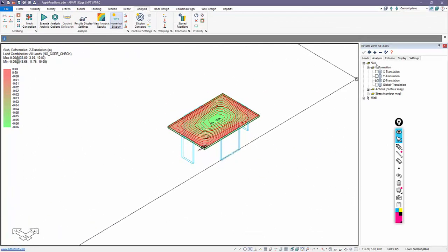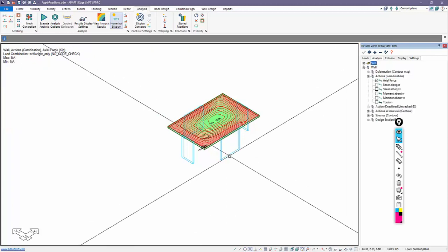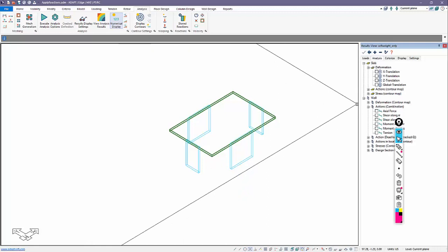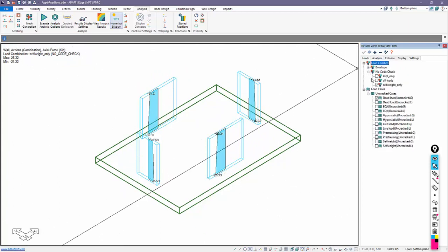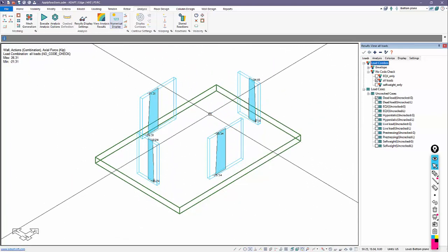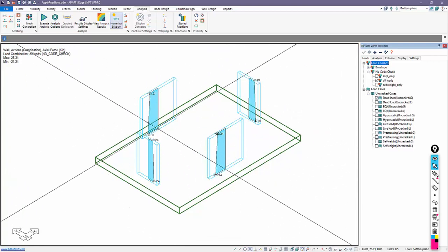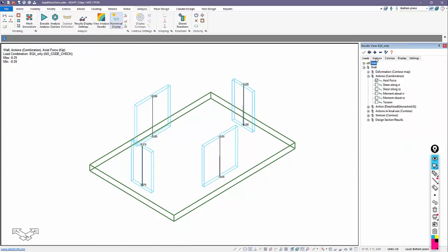Now that I have reactions in the walls, if I look again at self-weight only, for example, and I go over to analysis and I'll collapse this and expand out the walls. If we look at the actions, for wall forces, let me turn off the slab contours. So we can see here the axial forces. These are for self-weight only. We could change the combination and see axial forces, for example, for all loads. This is a global solution. So these are the reactions that would be applied to the mat foundation when we run this in single level with reactions. But these are based on a global solution. We could also check things if we look at EQX only. If I go back to analysis for the walls, I might want to look at the shear along the walls.